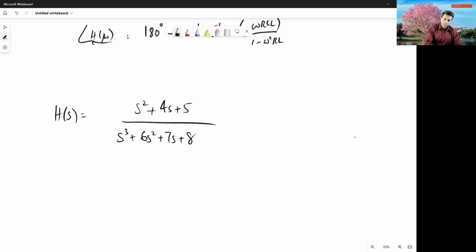All right, what is s? s is the variable of the Laplace transform, and it's generally given by sigma plus j omega, where sigma represents the transient variable. When a system is changing, when it starts or goes through a changing phase, for a brief amount of time there's a phase called the transient phase, in which it is still settling down to its final condition. And omega represents the frequency of oscillation.